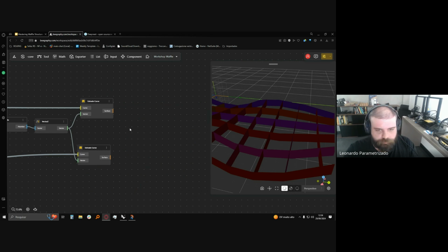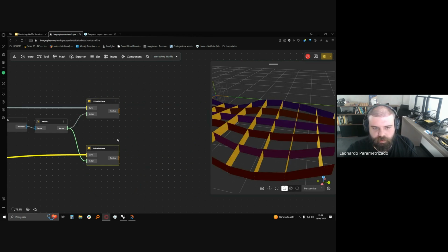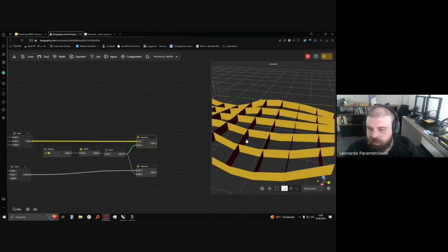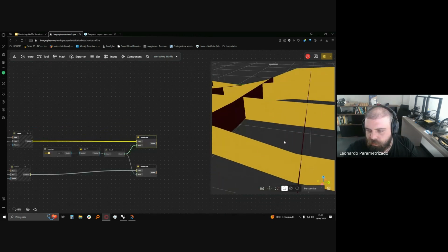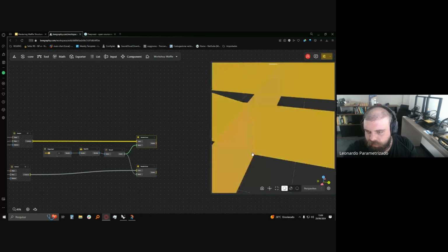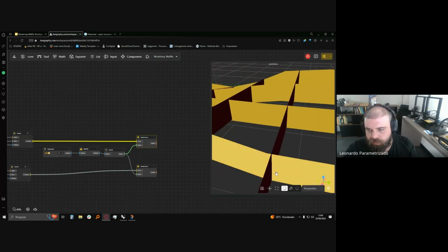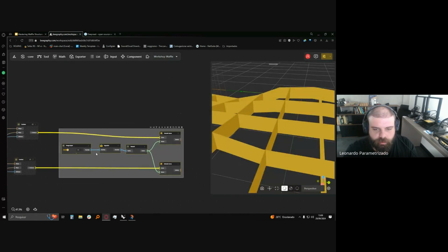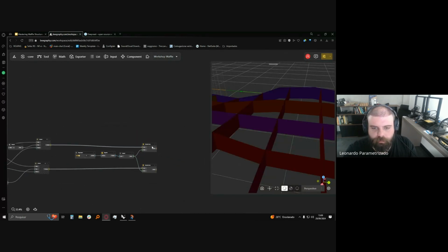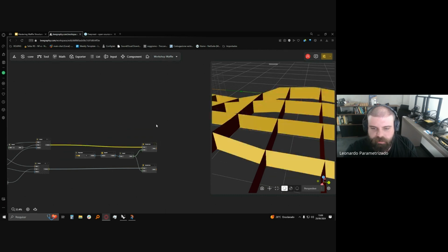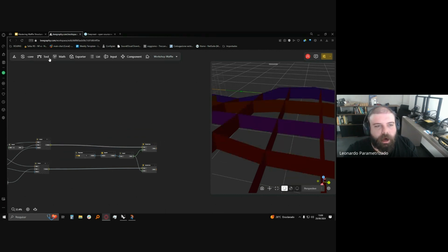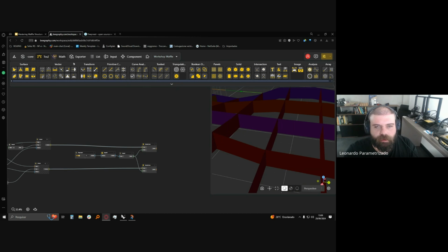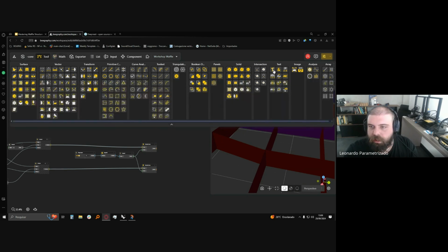So we've got our surface here. First of all, we need to have this intersection right here between these two objects. This is a workaround of how we can find these intersections. In the tool tab, under intersection, I'll be using this Intersect, surface and curve.